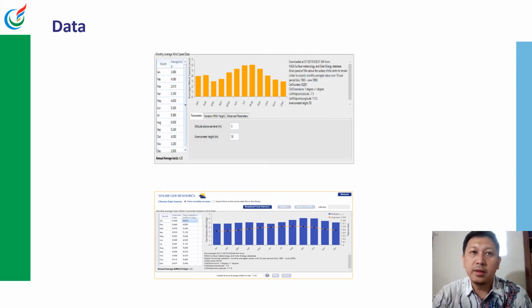4.28 meters per second. And solar radiation data in the Cepu area is obtained through NASA. With the help of HOMER, it will connect to the NASA satellite via the internet by providing the latitude and longitude of the research location. Solar radiation data in the HOMER simulation software requires years of data to be able to simulate a photovoltaic system, from the NASA data on solar radiation per month.